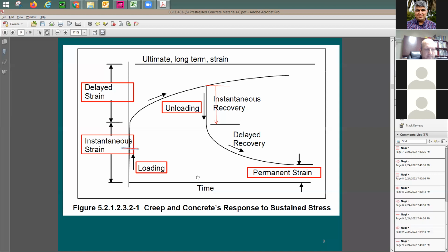Meaning, when I gave the example at the beginning, let's say that I have a beam, and I'm going to be loading it with, let's say, 10 kips as a point load in the middle. I just assumed that the total 0.5 inch is going to be elastic deflection. But you know what? Not the whole 0.5 inch is elastic deflection. Because it depends on the strain level I'm going to be approaching or reaching. You know that at the beginning, at the early stage of loading, you're going to be in the elastic range of the concrete. But let's say that I put a point load which is close to the capacity of the beam. So I know that I'm going to have some inelastic strain that's going to happen instantaneously without even waiting.